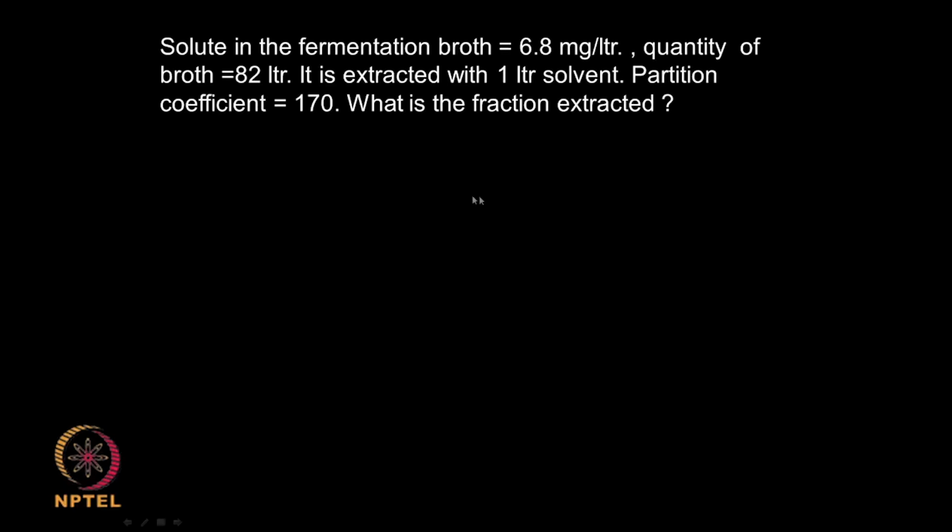In fact, that is what this problem is. I have a solute in the fermentation broth at 6.8 milligram per liter. This is your XF. The quantity of the broth is 82 liter, this is your F. 1 liter of solvent, this is your S. Partition coefficient is 170. So, what is the fraction extracted? First I need to calculate XR, I know XF, and then I can calculate the fraction extracted.